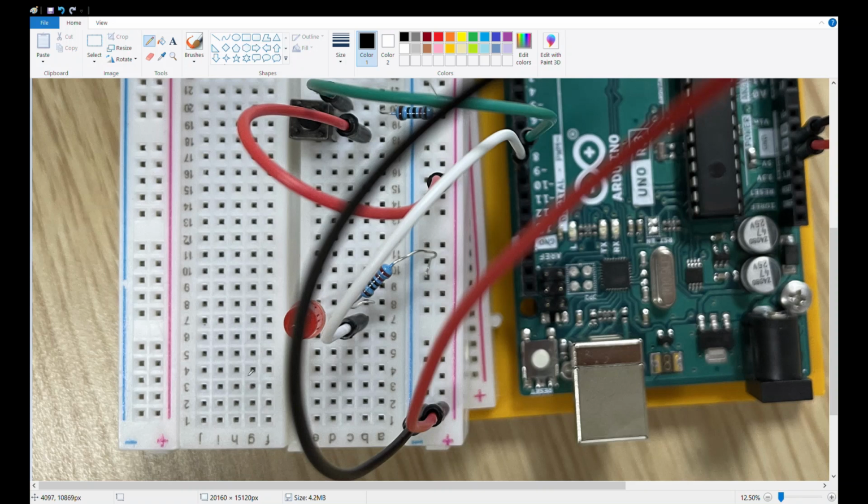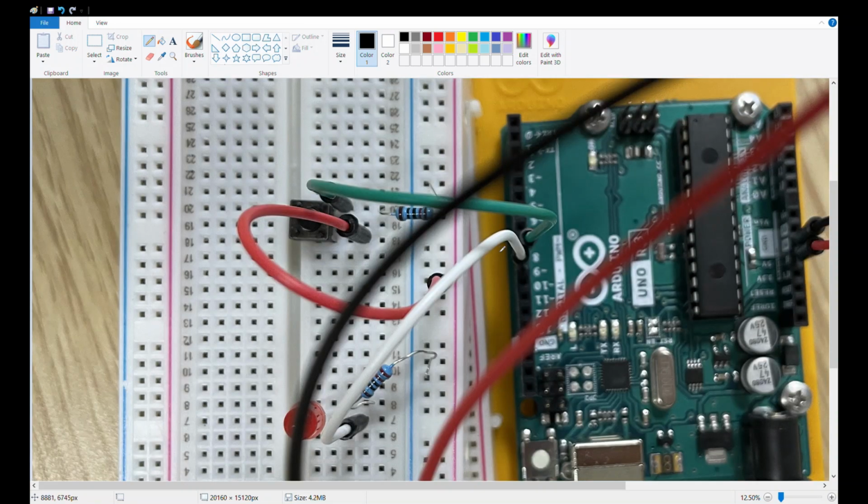the LED is going to get turned on, and we're making sure to wire it through a 220 ohm resistor as well to make sure we don't damage it. And so for the button component here, we have it wired directly to power, as well as through digital pin 8 as an input, so that when this button is pressed, this circuit between this red wire and this green wire here is completed, and this digital pin 8 input will detect a state of high.